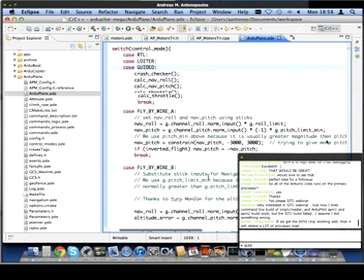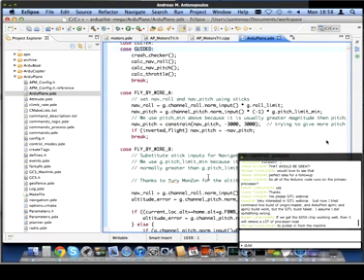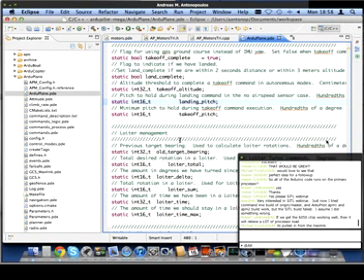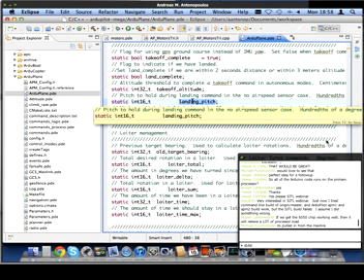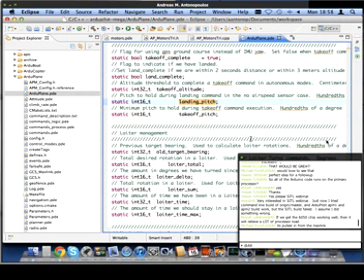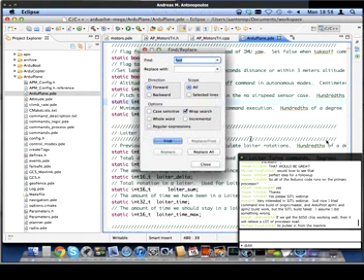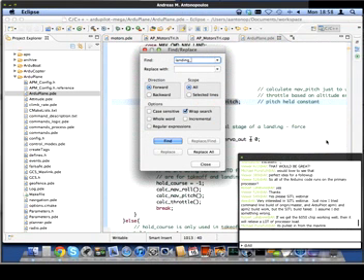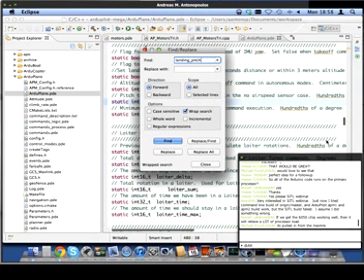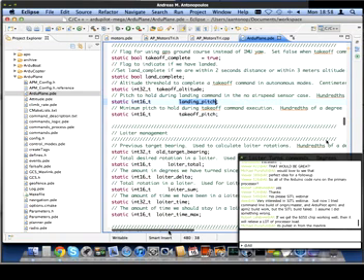All right. So you'll see the nav pitch gets set to landing pitch. But I can't find where landing pitch is actually defined. I see where it's initialized, but it's not defined anywhere that I can find. Okay, I got mute off? Yep. It's defined as an int16 at line 480 of ArduPlane.pde, but it's not set anywhere.